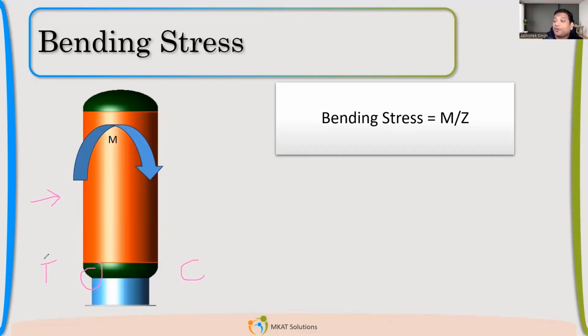Okay. So now if you combine with the dead weight, okay, here there is tension, but because of dead weight, there is a negative stress. Okay. So if I write W as a stress due to weight, so it will be T minus W. Okay. But this side, it's minus C minus W. Do you agree? Do you agree, guys? Yes. Yes, yes. So very simple, right? So this side, the weight is also acting in the downward direction, while because of the moment, there will be stresses coming again in the compressive. So here it will be addition. Okay, here it will be tension minus.